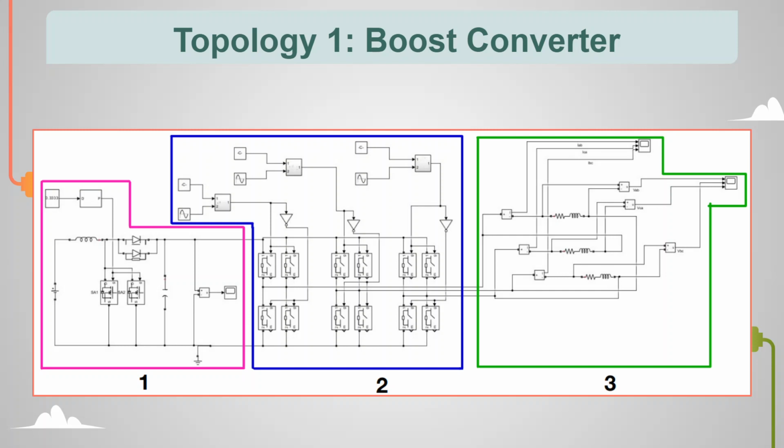If the boost stage was removed and the battery was directly connected to the inverter, it would result in overmodulation. Overmodulation maximizes the phase voltage, and in the presence of non-ideal components, such as the case of diode voltage drops and switching resistances, this would reduce the output voltage and the controls could not adjust the output any higher as they are limited by the losses.